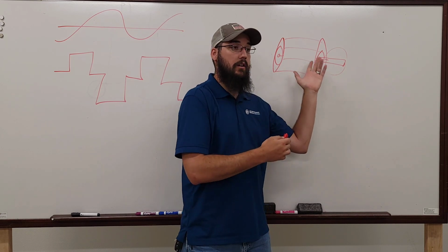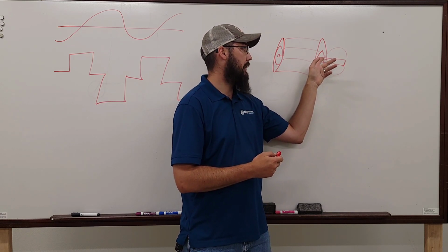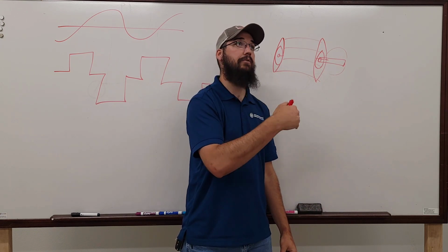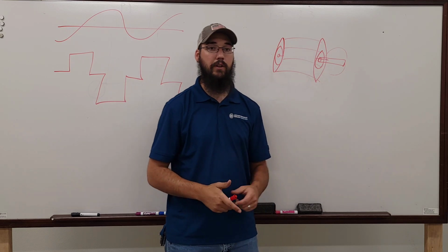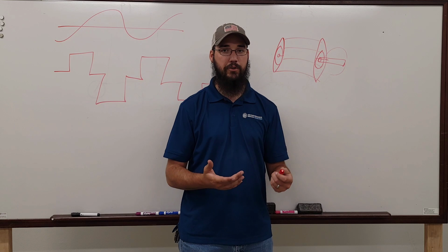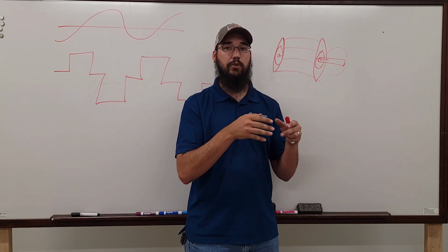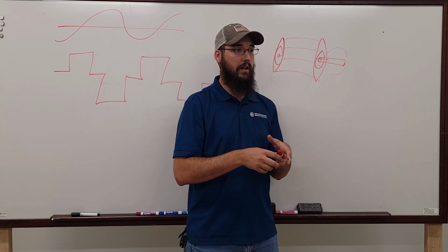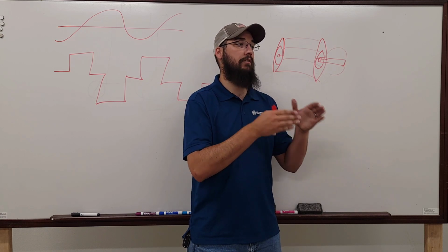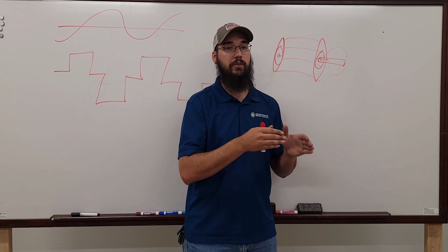So to resolve that, we put in a floating ground point. Okay, so the aftermarket ones that you can have installed, we take them to Hamilton or somewhere, have them put in or done, take it to any motor shop. They'll have a floating point touching the shaft, usually external to the motor, and that's all it's doing. Its sole job is to give an alternative source for discharging the rotor other than the bearing.